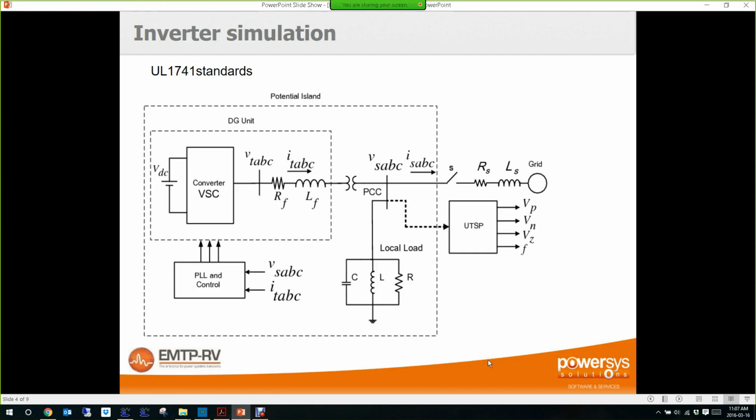And so then why is it so challenging? Because as soon as the switch opens, first, since no power is drawn from the grid, we barely cut any current. And since also the natural frequency of this load is 60 Hertz, even if we create a disturbance like that, there is no difference in the frequency. So it's completely invisible for the DG to see an event like that.